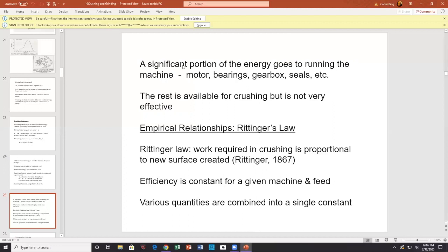The whole idea is you take the total machine, run it empty, and get a background power level with a watt meter perhaps, and then you run it full. Running empty will give you these, and running full will give you these plus the material. So doing a bit of subtraction there, you could get an estimate, not a reliable estimate, but reliability is another issue, on how much power you're actually putting into the material.